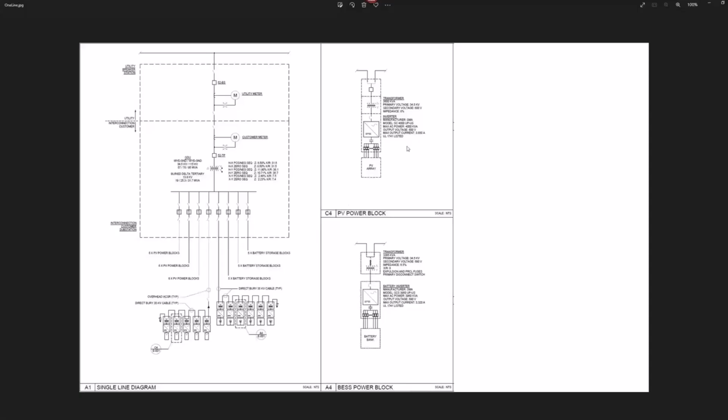And definitely, they use different inverters, even though the manufacturer is SMA, right? SMA is one of the, I would say, most popular inverter manufacturers in the United States, together with Sungrow and other manufacturers as well. So we use the SMA as an example. What we first need to collect from either the utility or the facility design is the one-line diagram, right? That will describe how the project is connected to the utility, how the project is constructed.